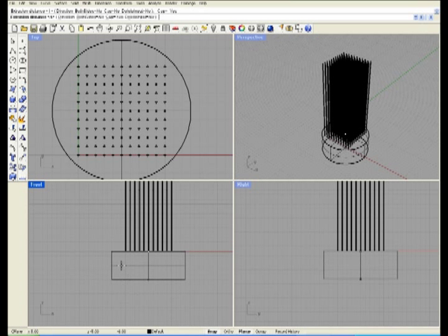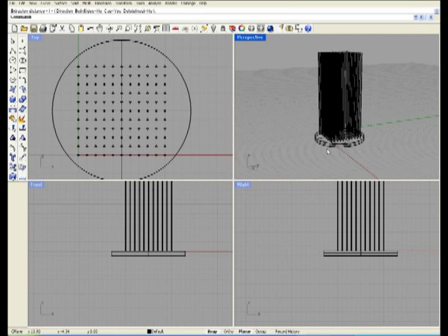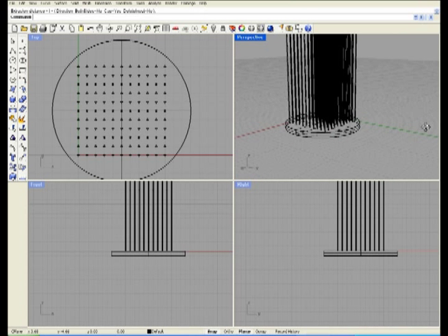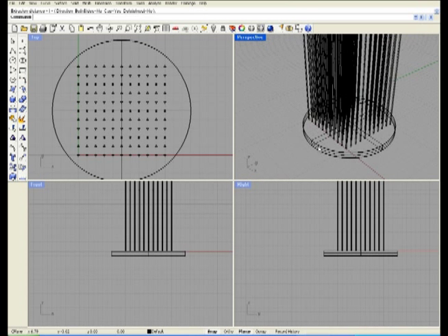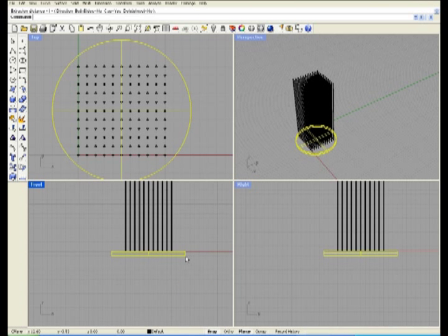In this case I'm going to maximize the front view, and I'm going to extrude it only 1 centimeter. When I have 1 centimeter, I'm going to click. Okay? And here I have my poly surface. It is a solid that is created out of a curve. And just like a circle, you can make any other figure and form a solid from there. Okay? So I'm going to have this poly surface.